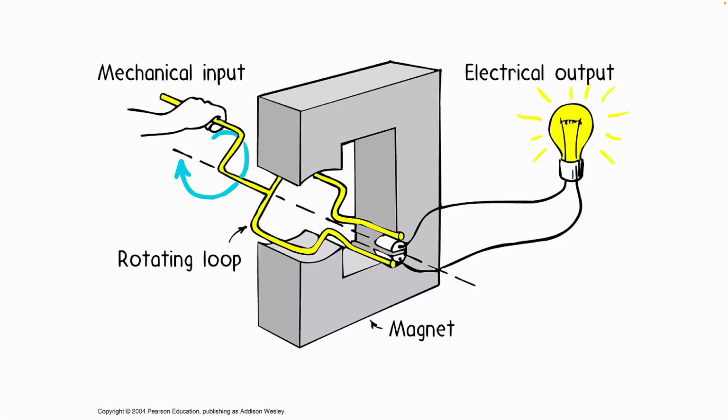The filament in one of those old-fashioned incandescent light bulbs literally just heated up. The filament's going to heat whether the current's going that way or that way. It doesn't matter, right? And if at 60 hertz, or 120 times a second, this current is flipping back and forth, are you going to see the light bulb's filament flashing?